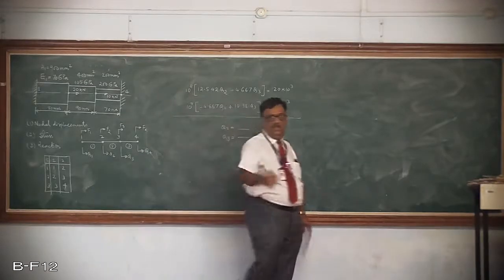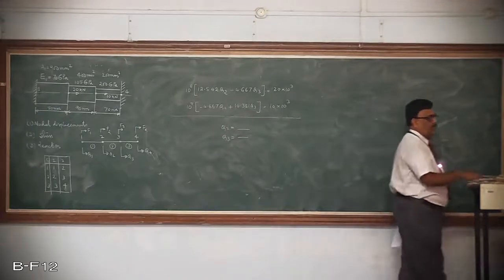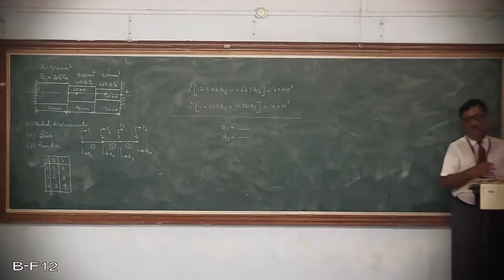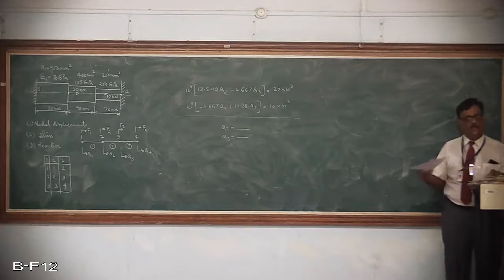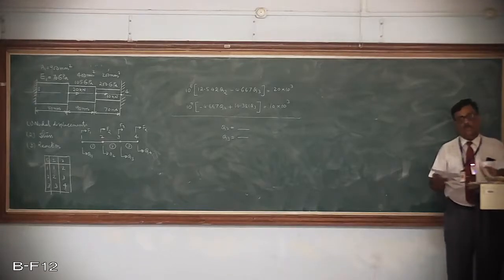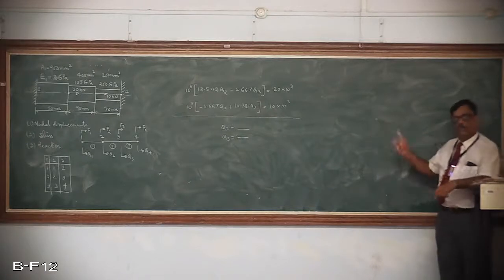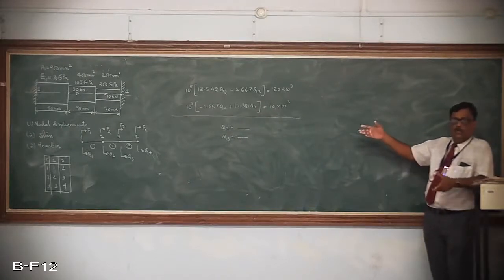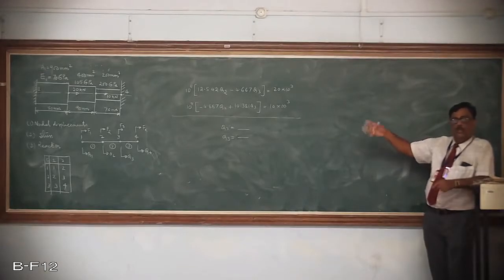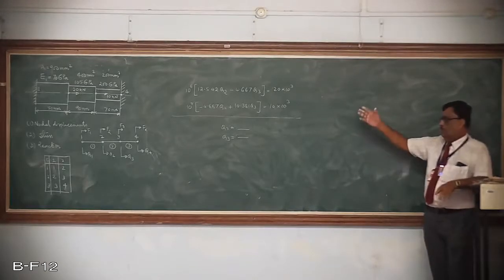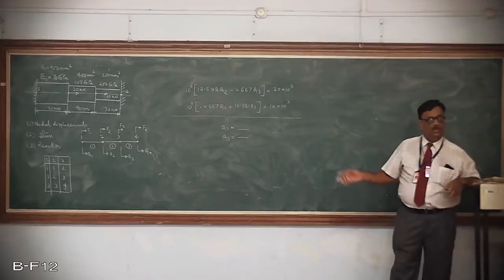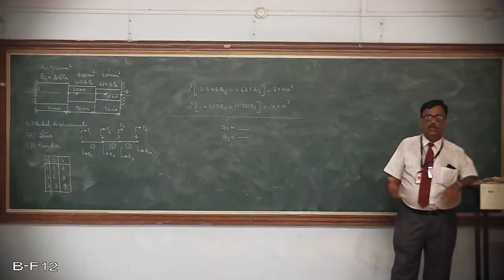Of course, if the number of degrees of freedom is more than 2, you will get 3 simultaneous equations, which can be solved if you have the provision in your calculator. If not, then by using techniques like the Gauss elimination method or the Cholesky method, one can solve these simultaneous equations and get the answers for a multi degree of freedom system.